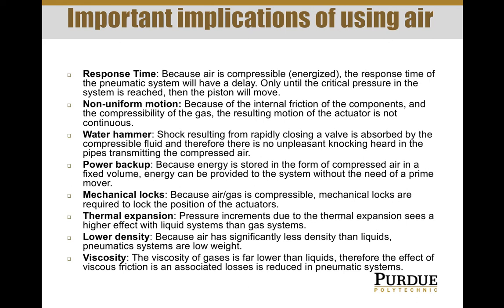Here's an advantage. Thermal expansion does not affect pneumatic systems as it does liquid systems, because the thermal expansion coefficient of air is relatively low compared to liquid systems. Then changes in temperature will not significantly increase the pressure of the system, therefore no significant change. Whereas in a liquid system, if you change the temperature, say by up to 50 degrees Celsius, you will see an increase up to 400 bar in a system. So that's very significant.